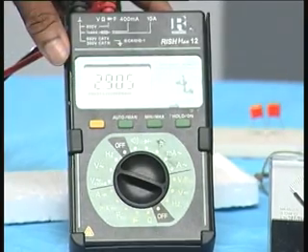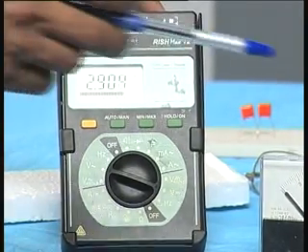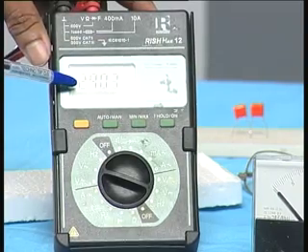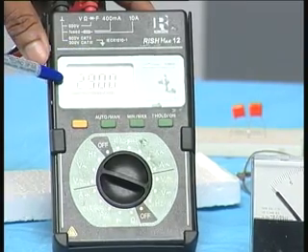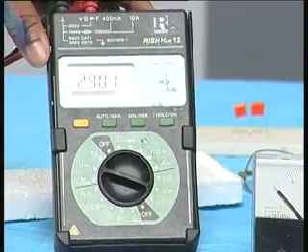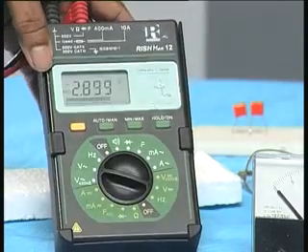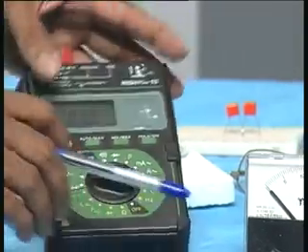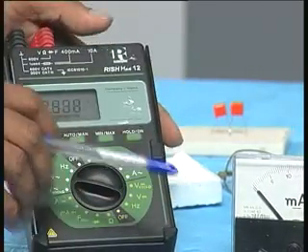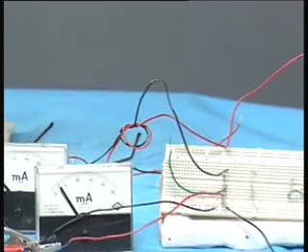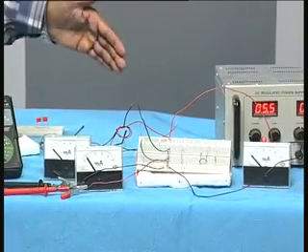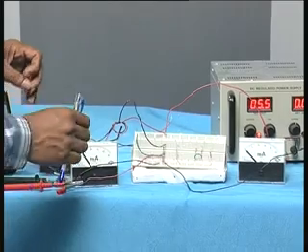And therefore, when I connect 6 volts to two equal resistors, the voltage across one of the resistors is found to be 3 volts. Similarly, you can see the voltage across the other resistor will also be equal to 3 volts. Therefore, the total 6 volts is divided among the two resistors connected in series, and therefore, the concept that the same current flows through both the resistors and series resistors divide voltage is very well understood by doing this.